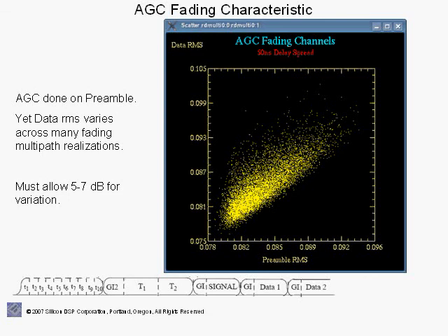Throughout the tutorial, we will discuss the effects of multipath fading channels on the performance of the receiver. Here we're basically showing some of the issues involved with AGC dealing with multipath fading channels, where we show how much margin you have to allow for the case where you have multipath fading channels with large RMS delay spreads. And we'll discuss the impact of multipath fading channels throughout the discussion of acquisition systems.